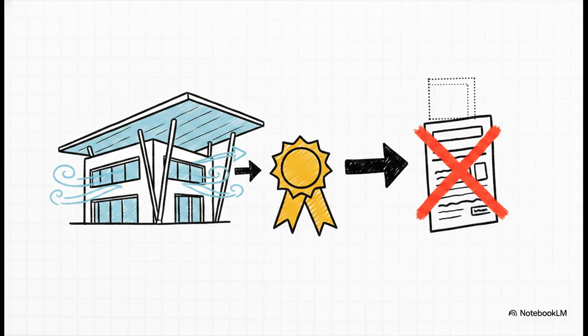Interestingly enough, this theoretical virtual energy is actually credited as energy savings in the system. Why? Well, because EDGE actively wants to reward inherently efficient bioclimatic architectural design. If you design a building that naturally stays cool without AC, you get credit for the energy you're avoiding. However, the software makes sure to remind you this virtual energy won't actually reduce your current utility bills, simply because the HVAC system isn't installed in the first place. It's just a really clever way to measure structural thermal performance completely independent of the mechanical equipment.